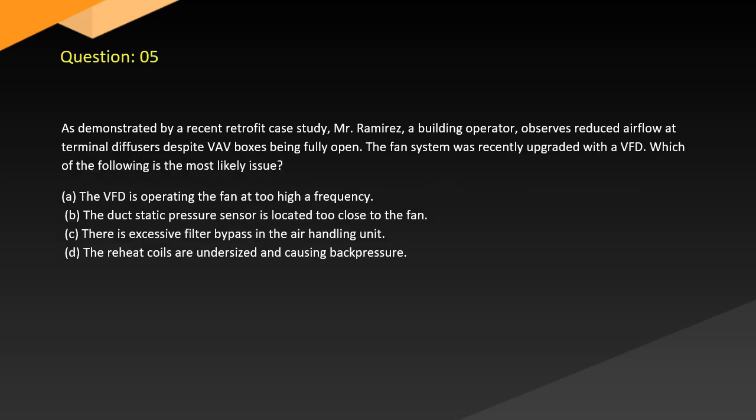Question 5. Demonstrated by a recent retrofit case study, Mr. Ramirez, a building operator, observes reduced airflow at terminal diffusers despite VAV boxes being fully open. The fan system was recently upgraded with a VFD. Which of the following is the most likely issue?